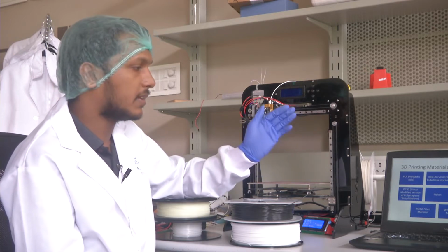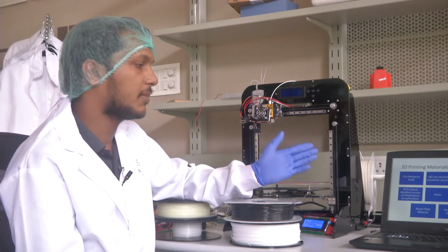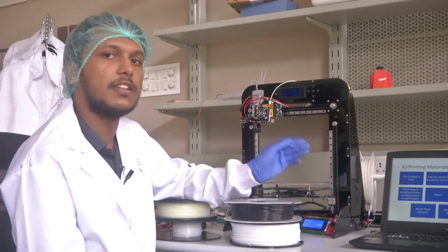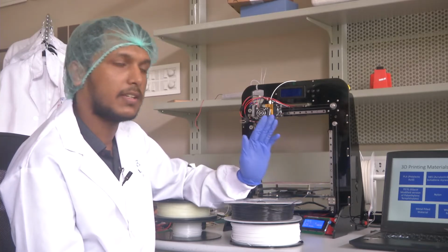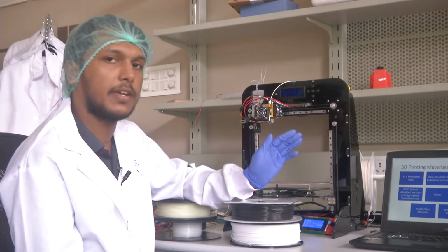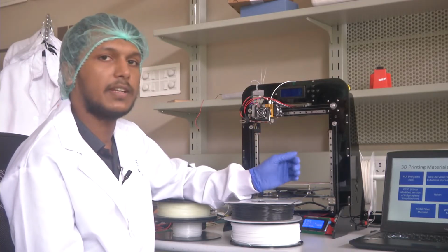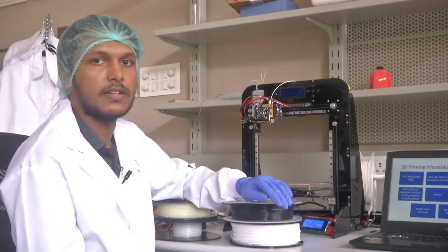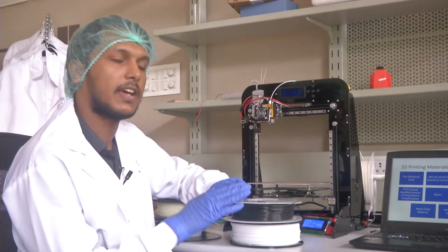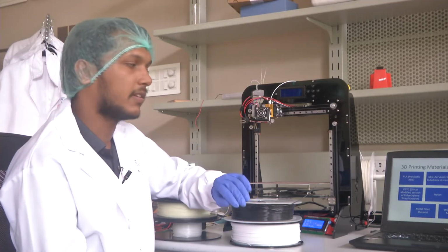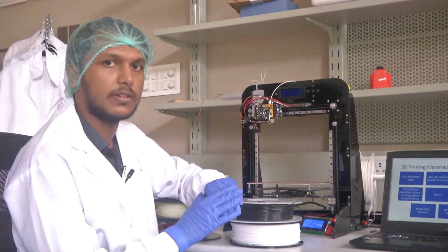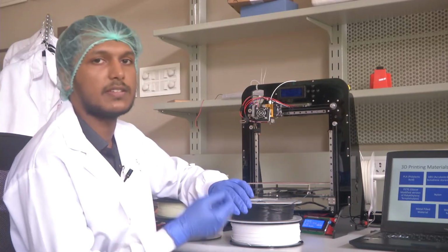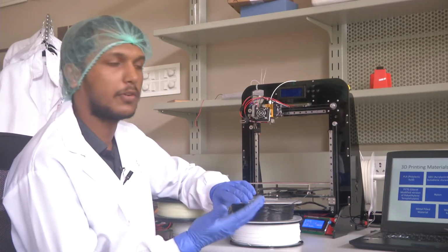Wood filament material is also similar to the carbon fiber or metal filled material. Fine particles of wood are infused in PLA or ABS material and can be used for making objects. Wood filled material has one specialty, it can be easily sanded. So using sandpaper we can easily sand the outer surface and make the finish look good. The appearance of the wood filled material will be similar to wood.